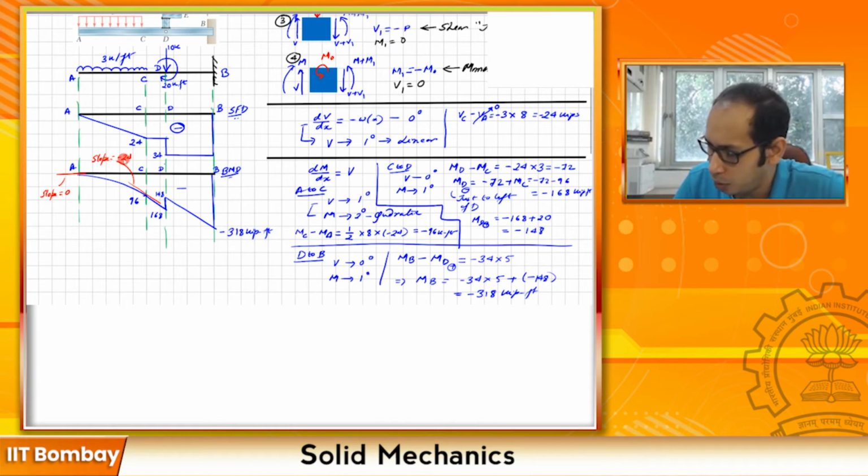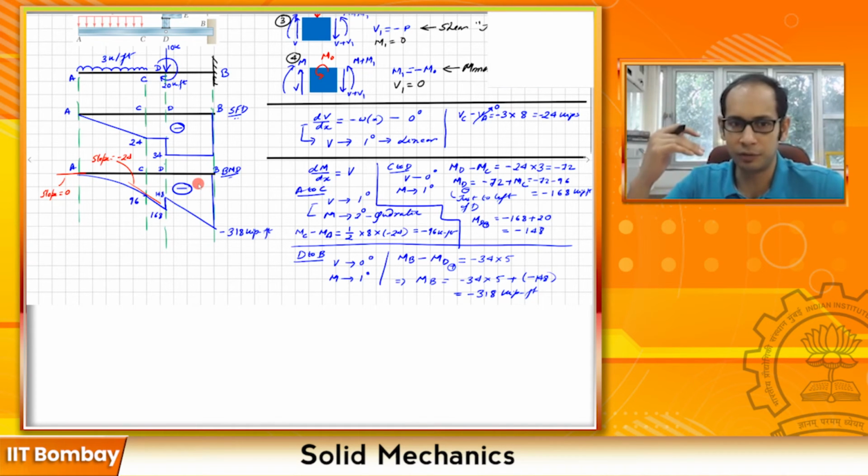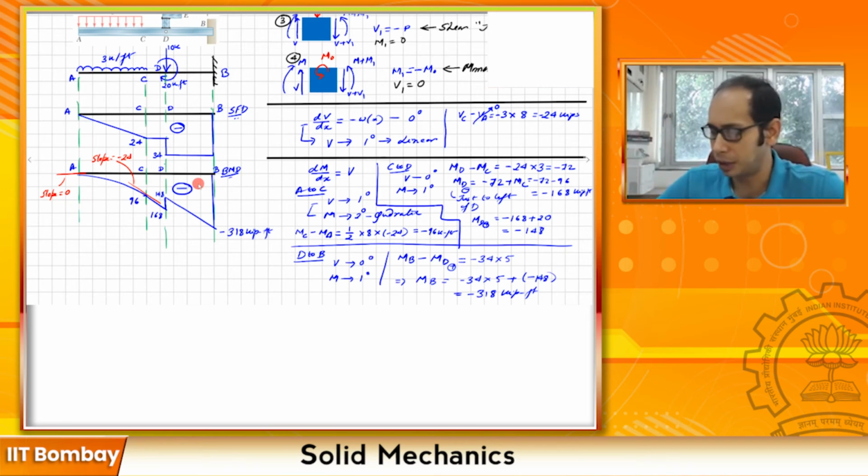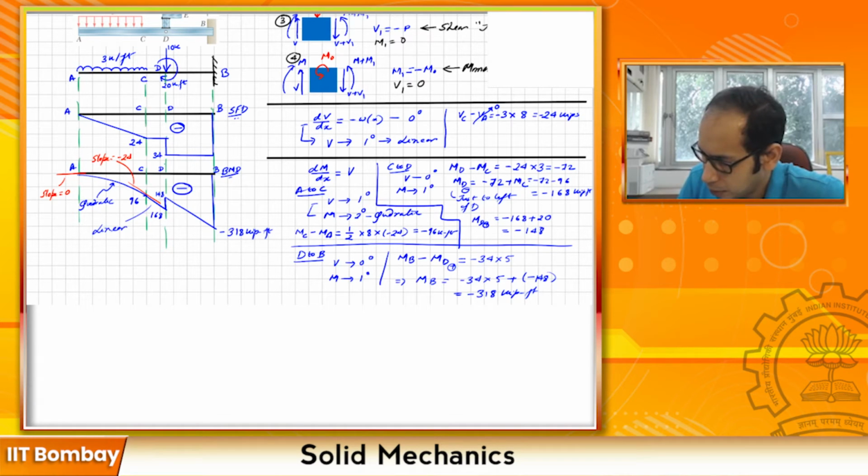So my whole bending moment diagram is also a negative diagram. Now, as I said, you can mark the negatives or you can leave it, that's fine. If you write the negative here, I know that you mean that all the values below that horizontal line of the beam are negative. So let's compare what we got. Let's write these ones. So this is quadratic, this is linear, this is also linear, and this is the place where you had the jump.